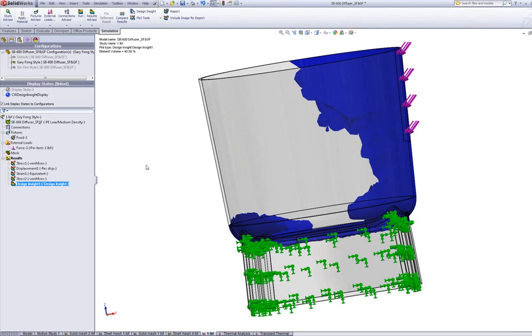which means this model needs to perform very robustly. Let's say I have a paper clip that is a class 3 device, and it's going to be embedded into a patient's body. That particular device needs to operate 9 times the amount. Let's say I have a particular loading on this model. I need to be able to apply 9 times that amount of force on the model before it breaks, in order to have some insurance that it's going to operate successfully in the human body. So this factor of safety value is important for many applications.